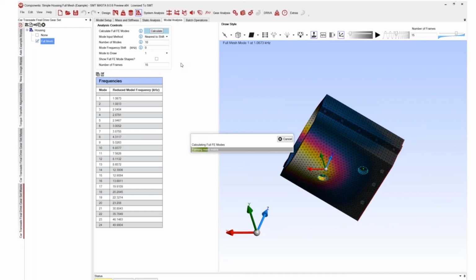Just while that's running, I'll answer one other question that's come up. For the T calculation, if you're using the basic or advanced LTCA, MASTA will ignore the teeth in your FE model, and it uses a separate mesh or a separate stiffness for that LTCA calculation. As I'll show in a second on the final slide, that is something we're working on improving in the future for MASTA, to try and share the same FE model for doing the T calculation with the deflection calculation.